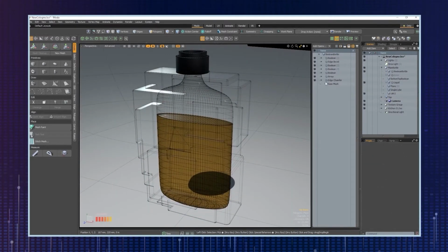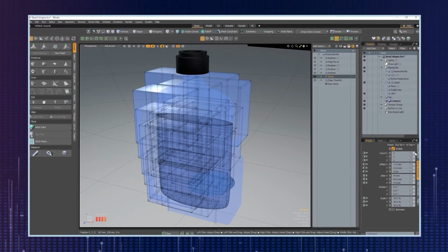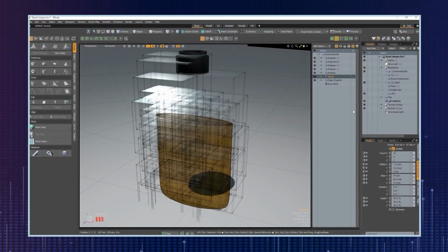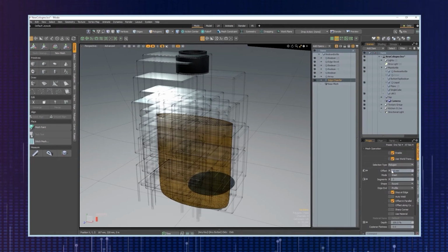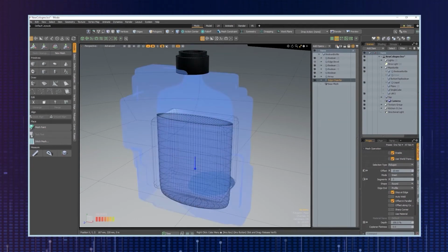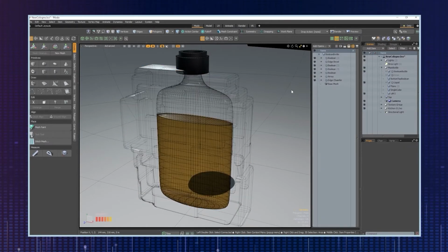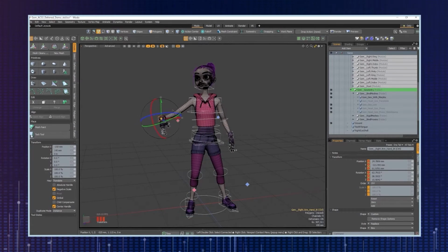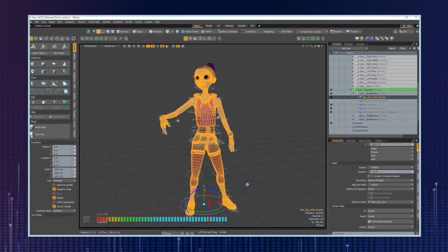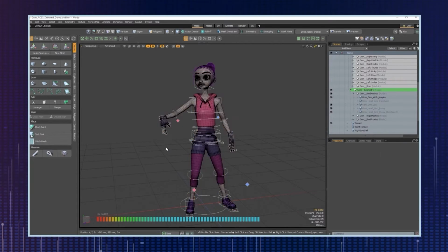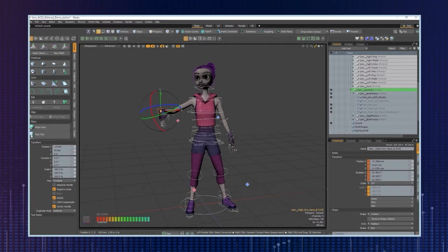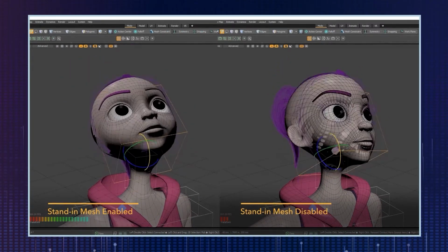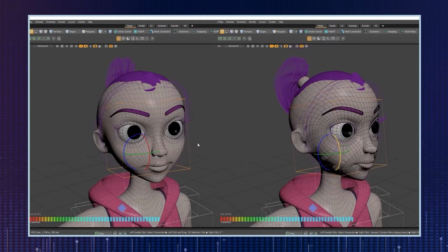If a user is modifying channels on a mesh op, that modification affects operations that are above it and the entire stack is re-evaluated. When enabled, paused evaluation disables all evaluation, allowing a user to quickly make a couple of adjustments that won't update until pause has been disabled. Furthermore, deferred evaluation can be leveraged on deforming surfaces to temporarily replace a high-res mesh with a low-res stand-in mesh when deformers like bones are being manipulated. This allows users to rapidly edit deformers with high interactivity and without sacrificing visualization of the high-res mesh.